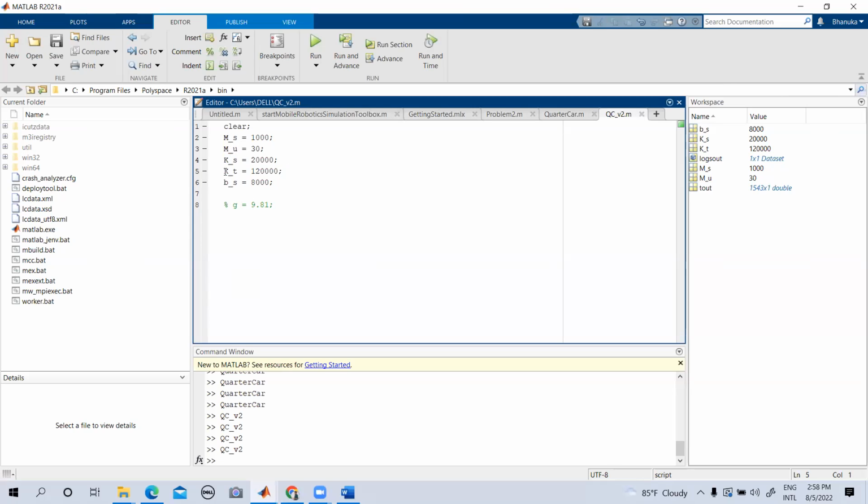The unsprung stiffness or the tire stiffness is also sort of controllable, but I wouldn't say it's exactly controllable, because as a manufacturer you get ready-made tires, right? So you can't actually control this. But by controlling only these 2 factors, you can optimize the system and say, okay, these are the features we want the vehicle to have to obtain this particular response, right?